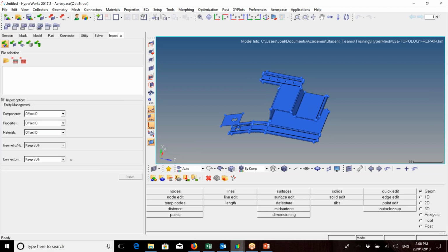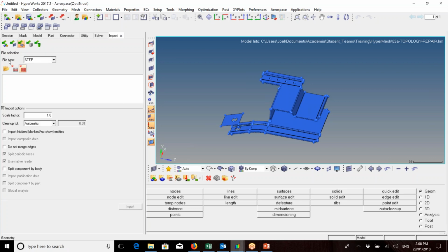So by clicking on any one of those, you are then able to select between these in this little section here. So the model will be as a standard HyperMesh model, which, unless you're working from CAD, you generally won't have this. So with your CAD, you'll want to be looking at import geometry, and then you can choose your file type. And through here, we've got all these different types of files. You've got STEP files, SolidWorks, Parasolids, you've got your JTs, Inspire, which is what we covered last week, IGES files, CATIA, Axis, or you can do an auto detect.